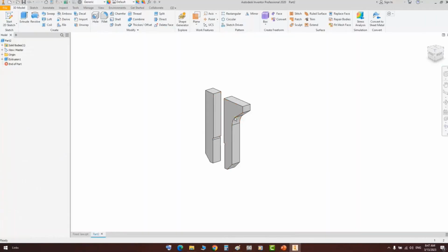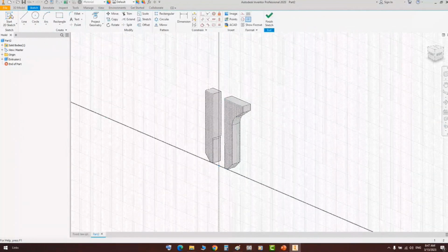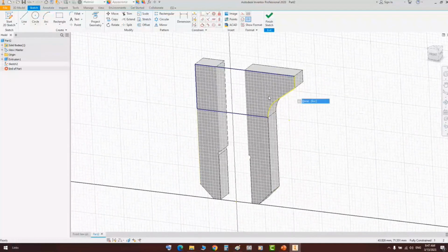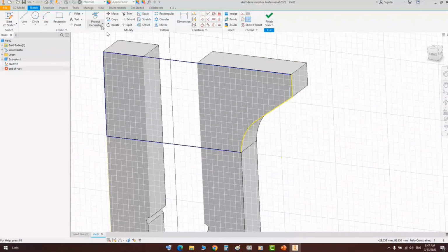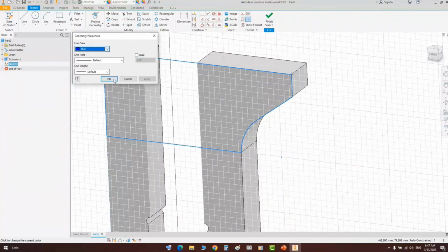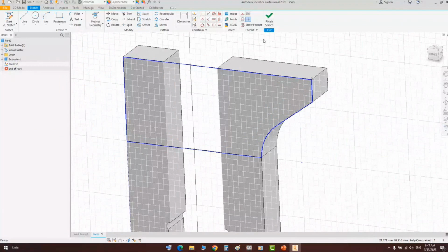Okay, so to create it, we can select that face, and from here select create 2D sketch. And now we can make a project geometry for that. So select those lines, convert that one, and close the sketch like that. So that's, as you can see, the section here. And for the yellow colors, which are created by using the project tool, we can convert all colors in this sketch to blue colors to make them visible in a good way.